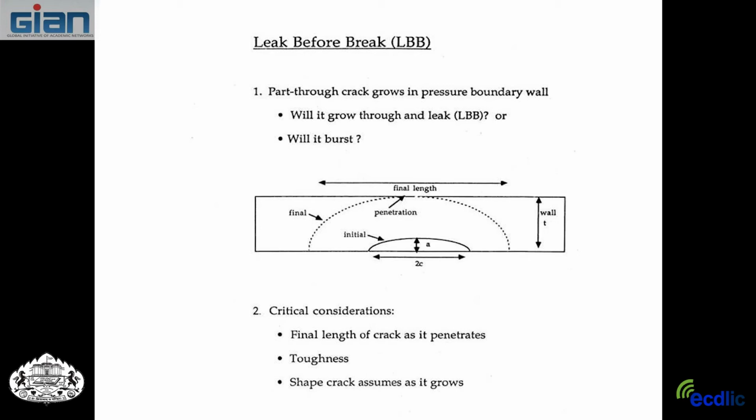But the danger then is before it leaks, it could burst. So once it gets to the point where it would leak through, and you have to assume some section here, you would pick a final crack size and use a K1C with a center crack. You assume that this is a big crack here, and then do K1C analysis and see if this crack has reached K1C given the internal pressure and the size of the crack or not.